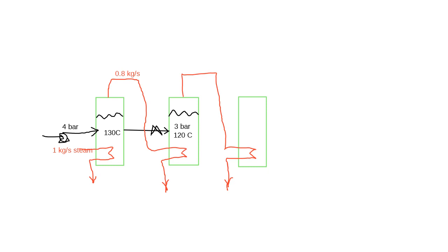It's getting more and more concentrated. And all the time that you're evaporating, crystals will start coming out. Go to a line, and we go from there to there. We reduce the pressure again. That's a better valve. And now we might be at 2 bar in this one, instead of 3 bar. And we might be at 110 degrees C.